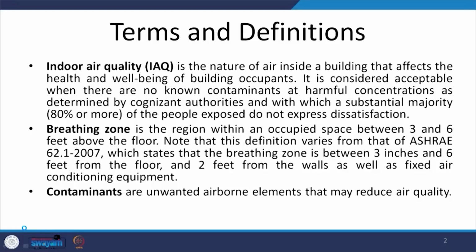The next we have breathing zone. It is the zone which is defined inside the building of the occupied space. Different codes define it differently. As per ASHRAE 62.1 2007, it is defined as the space between 3 inches and 6 feet from the floor, and it is at a distance of 2 feet from the wall. Other codes define it differently, but it is the air space where the occupants largely breathe the air from. So, this is what the breathing zone is.